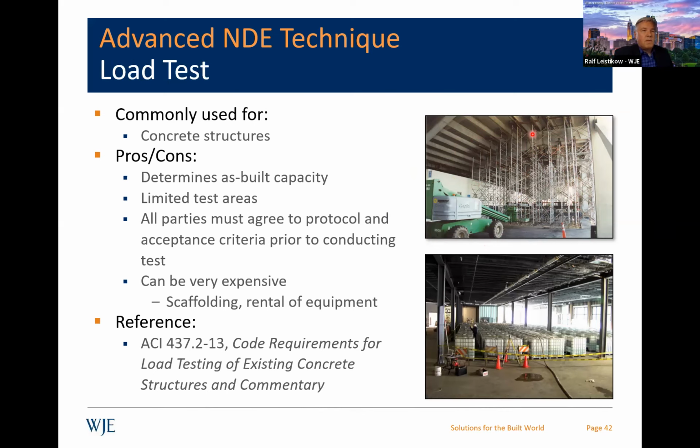Originally, we were going to look at adding loads or water, but we just couldn't get enough of it on there, and they're finished suites up top. So we had 3 load points. We used some Dywidag bars and created this frame. It's not super visible here, but we used soil anchors and pulled the structure down. There were some existing retrofits, if you've ever been out there, and there was concern that those weren't working, and they actually weren't. We put in another supplemental retrofit that's not very visible, but there were concerns about cracks right in the intersection here.